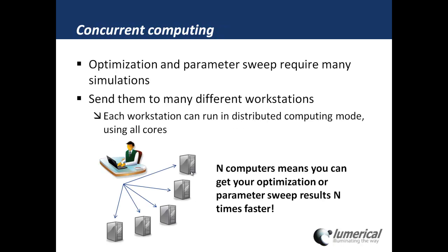Now, also talking about optimization and parameter sweeps, generally when we're doing that, or almost by definition, we require many different simulations. And so what we'd like to do is be able to not just get each individual simulation running as quickly as possible, but actually get all of our simulations as a whole running as quickly as possible. One really convenient way to do this, if you don't have access to a high-performance cluster, if you have access to a number of workstations on, say, an office network, which is quite slow, is to actually send out each individual simulation to a different workstation.